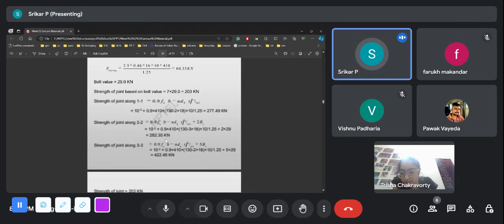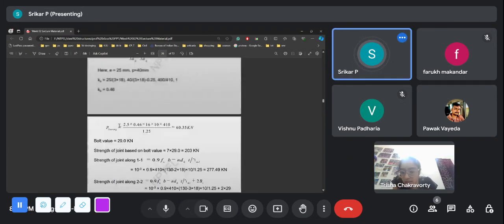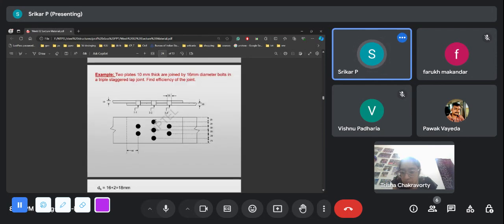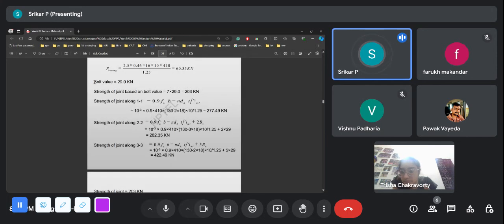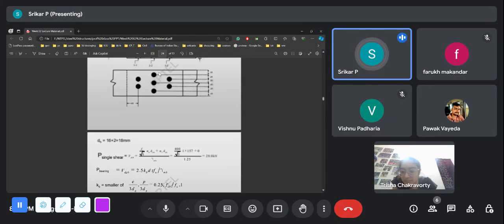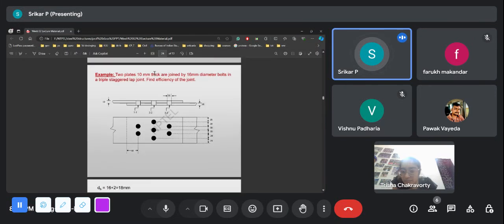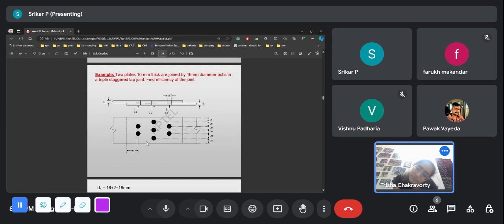Here we are talking about the joint. We're talking about where the plate actually fails. Actually, I think we have gone to the bolt failure. Here we consider the bolt value failure, and we are talking about only the joint failure. Again, if we consider joint failure, there should be failure of these three bolts along with this section. But we are considering these two bolts and this section.